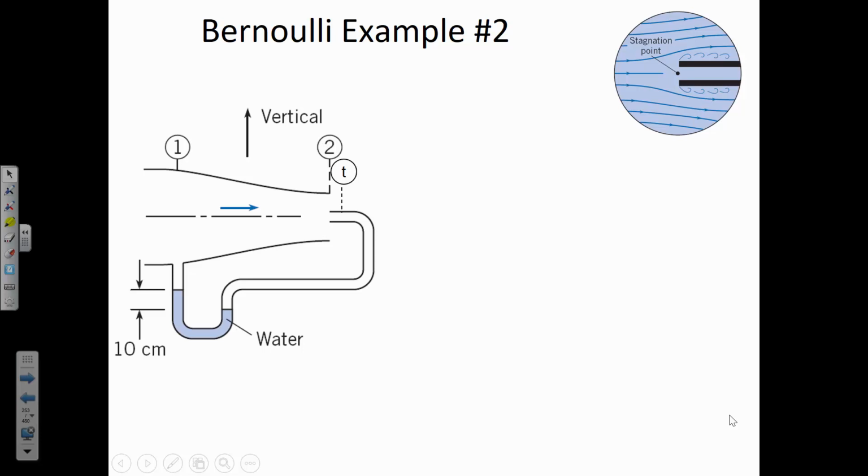Okay, so as the flow is going from 1 to 2, the energy is constant. It's just changing form. So we had low velocity here, but high pressure at 1. And then as the velocity increased, some of the energy changed form. So that energy that was existing as a lot of pressure before, some of it went over to additional velocity head. So at 2, there's still the same amount of energy, it just changed form.